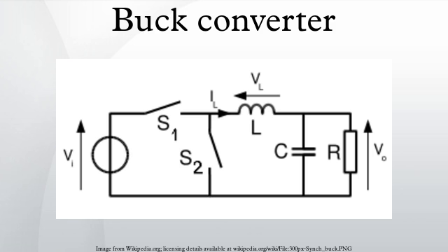Without actual numbers, the reader may find the usefulness of this substitution to be unclear. Consider a computer power supply, where the input is 5 V, the output is 3.3 V, and the load current is 10 A. In this case, the duty cycle will be 66% and the diode would be on for 34% of the time. A typical diode with forward voltage of 0.7 V would suffer a power loss of 2.38 W. A well-selected MOSFET with RDSON of 0.015 ohms, however, would waste only 0.51 W in conduction loss. This translates to improved efficiency and reduced heat loss.